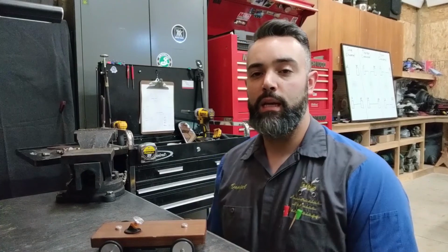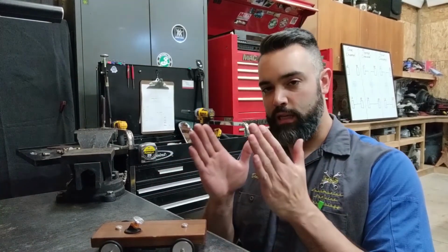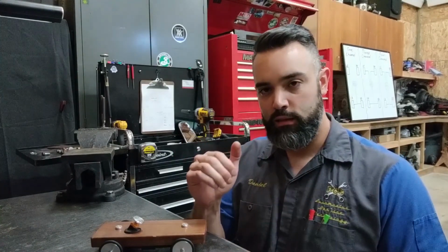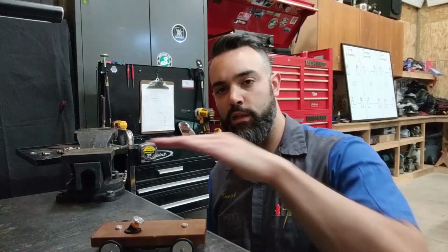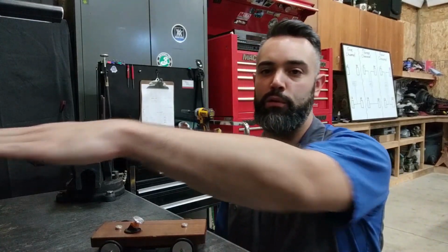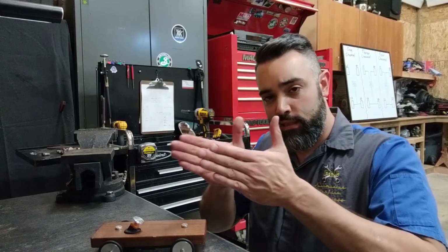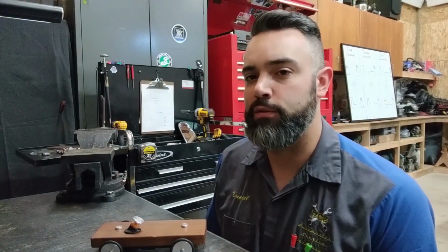a lockup condition. When a tire is rolling across a surface, it has directional stability to it. Once that tire locks up, or the brakes stop the tire from moving, but the motion of the vehicle continues moving forward, that tire is going to stop and slide. When it's sliding, there is no directional stability to it.